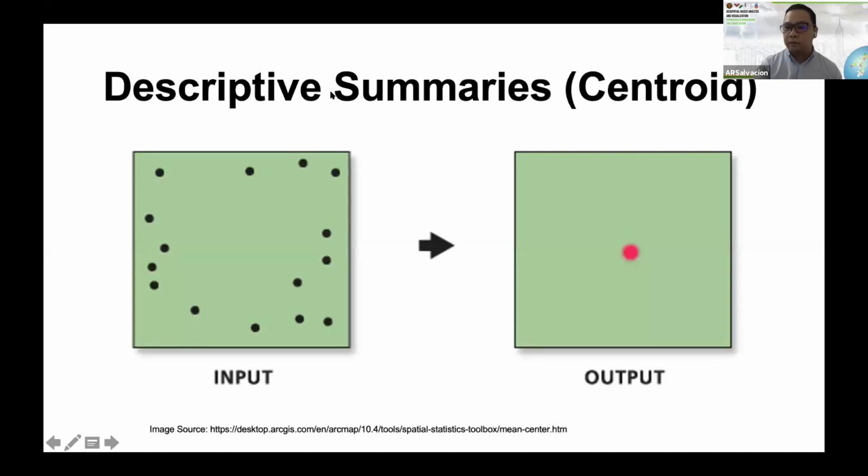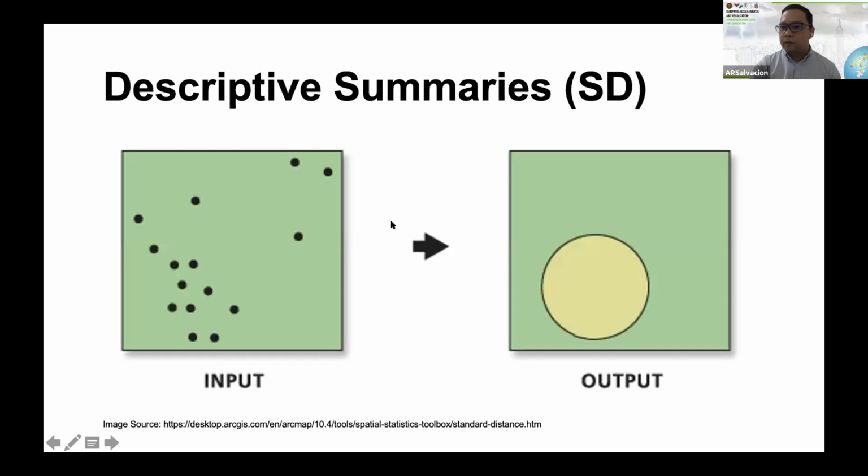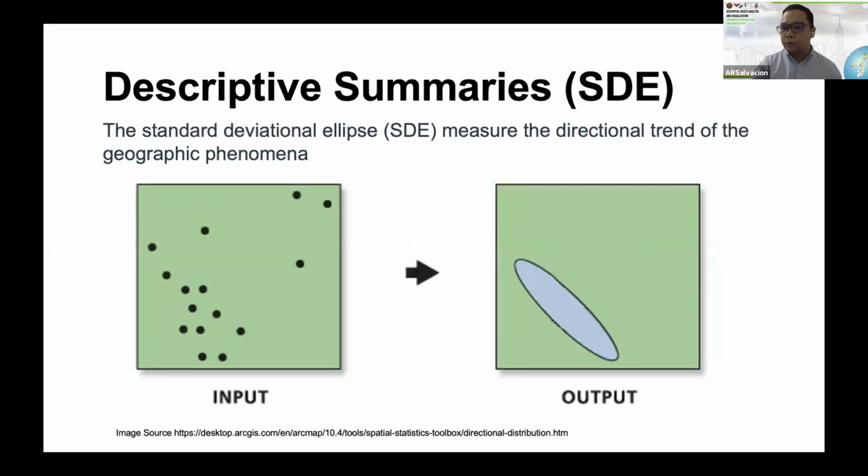You can measure that, the geographic center for this village, this municipality, etc. You could also do the standard deviational ellipse. So you could see what's the standard distance of each of these houses from the settlement center. And you could also do trend analysis. So what is the shape? What explains the shape of the settlement?